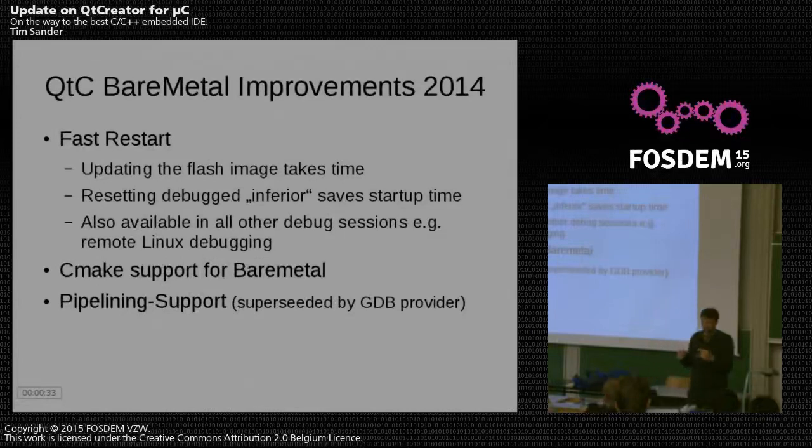And then, especially if you have a little bit more code to flash and your hardware debugger is not the fastest, depending on your setup, it might take a while to get you again to this position, and having fast restart helps for that. Fast restart is also enabled in all the other GDB backends.